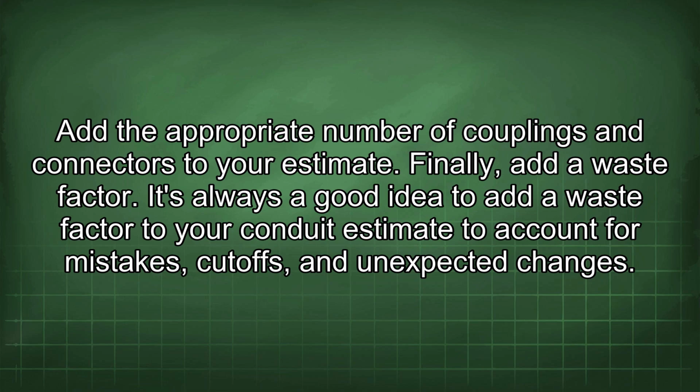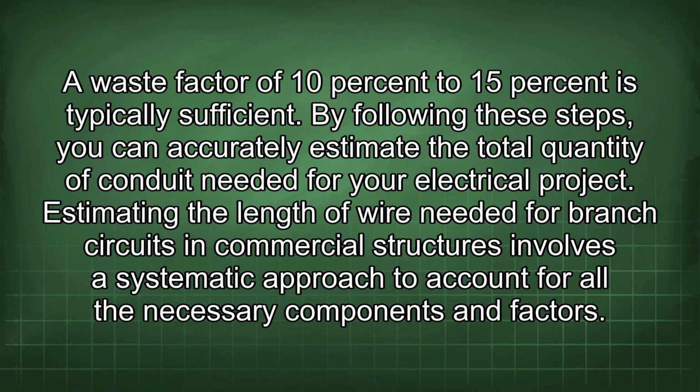Finally, add a waste factor. It's always a good idea to add a waste factor to your conduit estimate to account for mistakes, cut-offs, and unexpected changes. A waste factor of 10% to 15% is typically sufficient. By following these steps, you can accurately estimate the total quantity of conduit needed for your electrical project.